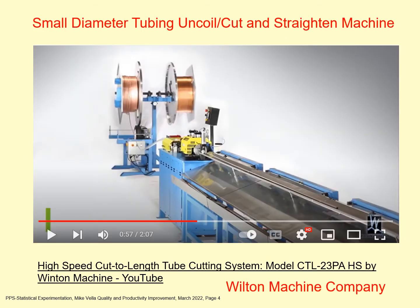Here is a typical small diameter tubing uncoiled cut and straighten line. I took this picture off the web from the Wilton Machine Company. If you're interested, you can visit them at that site. How this works is you start with coiled tubing, and you can see there's 2 coils back there. The machine's running off the coil to the left, and in order to have a continuous process, there's a splicing operation. When that first coil is completed, the turnstile rotates, and then the second coil is spliced on so you can have a continuous process.